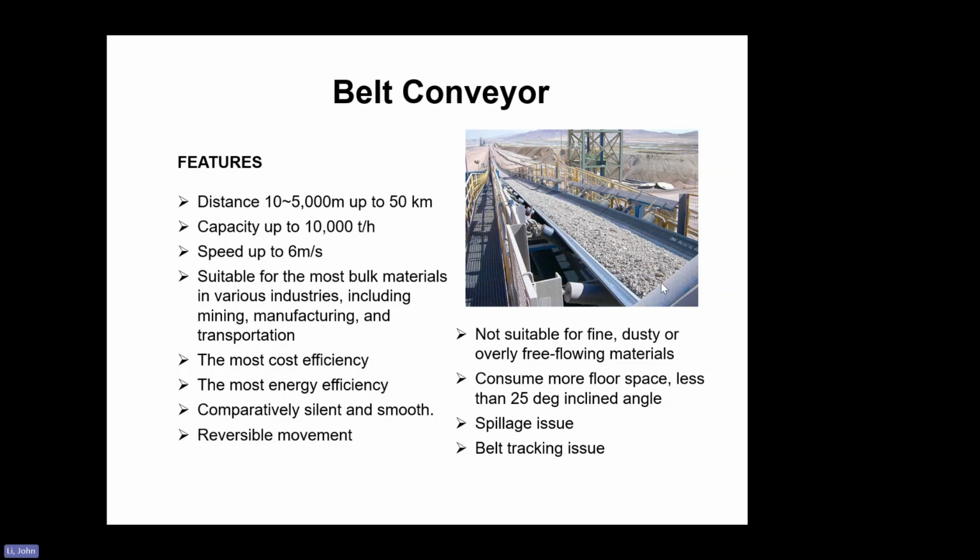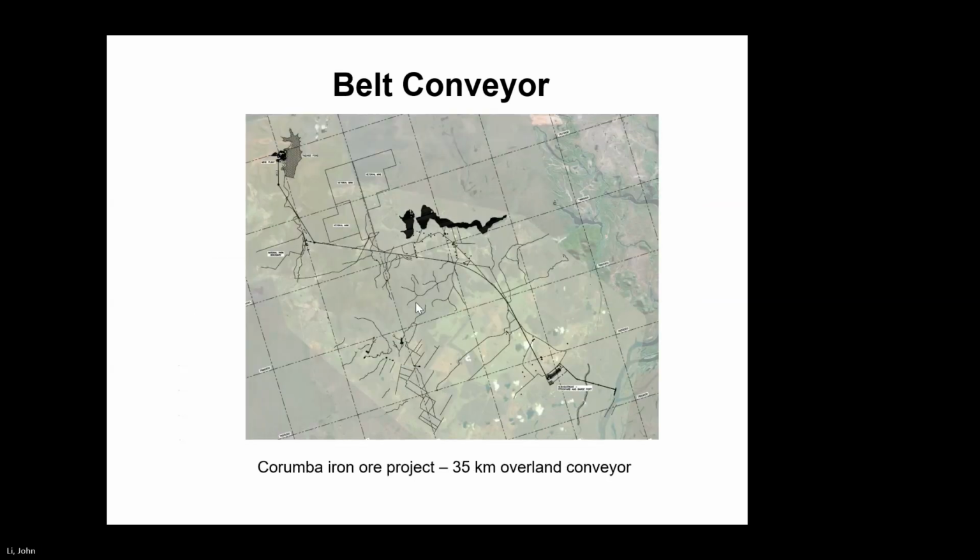If we do not consider wind, on the belt there will be no dust generated. Say there is no wind. So there is always a problem at the transfer point, from belt to loading, or discharge to other equipment or the ground. So that will be the issue at the transfer point.